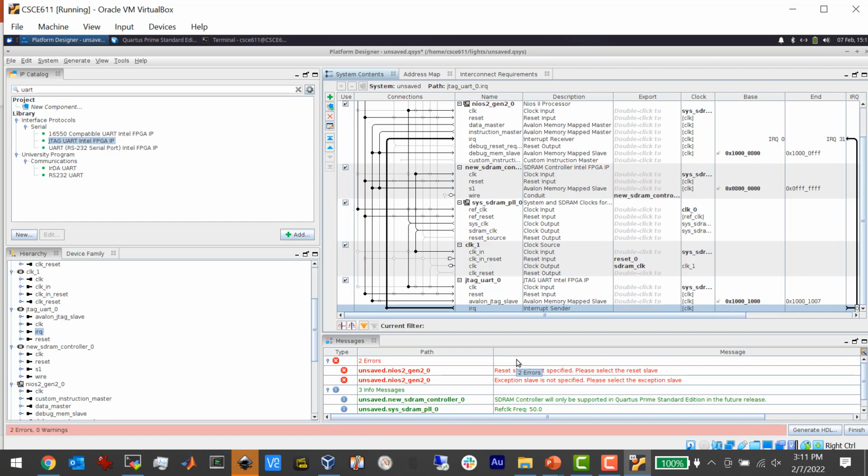Now, by the way, if I were running Linux on here, Linux would have to know these before it even boots the kernel, which is why, in order to boot Linux, you need a kernel and a device tree file. You need two things to boot a Linux machine. This is the information in the device tree, these address ranges for the peripherals. Okay?